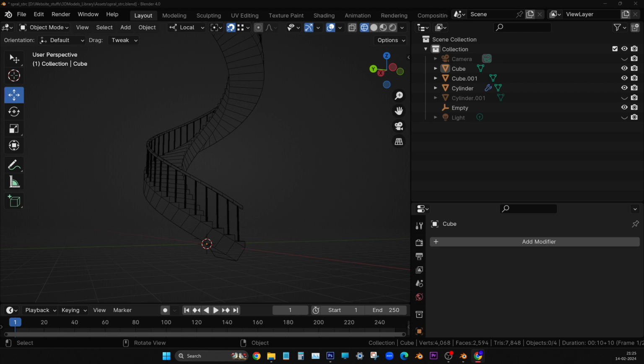Now we have selected this face. This is a perimeter. So similar perimeters we have to select using some tool, so that our work will be saved. You have selected one face, and go to Select, and in the submenu, Select Similar is there.